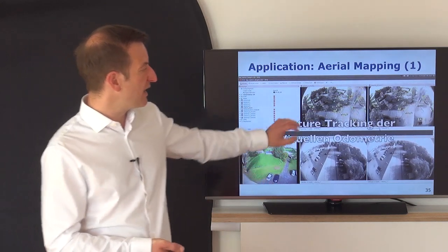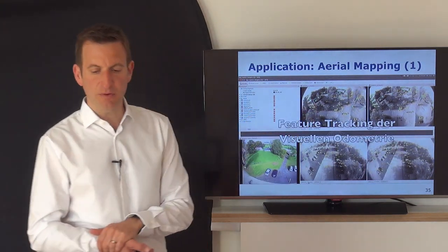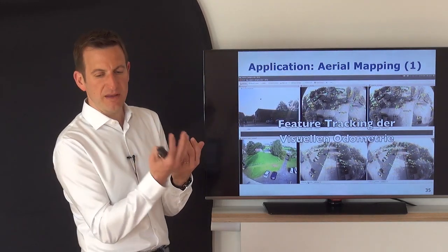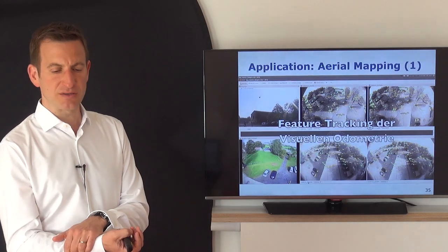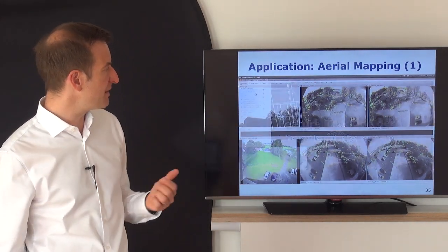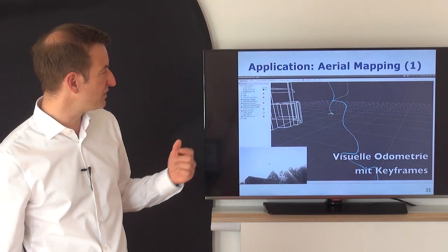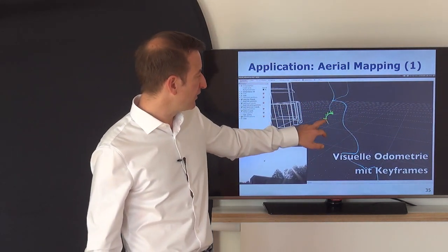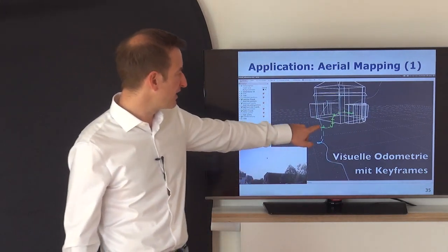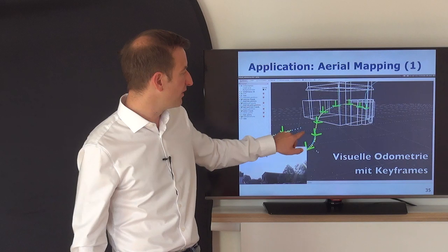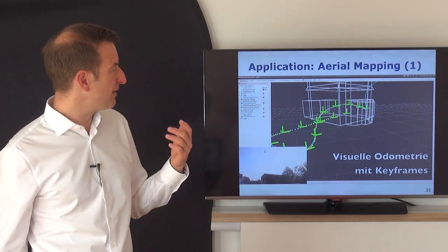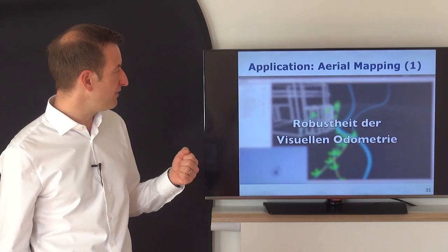That means we can extract features or kind of distinct points in the environment and then track those features over time to estimate where the UAV is actually flying, and can enrich the GPS and IMU information with this visual information. So it means we can see this here illustrated in green, these reference frames where the orientation information of the UAV can be estimated.